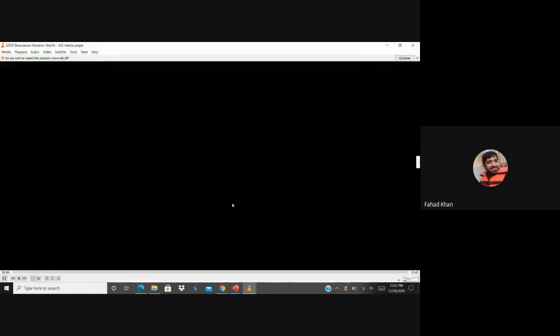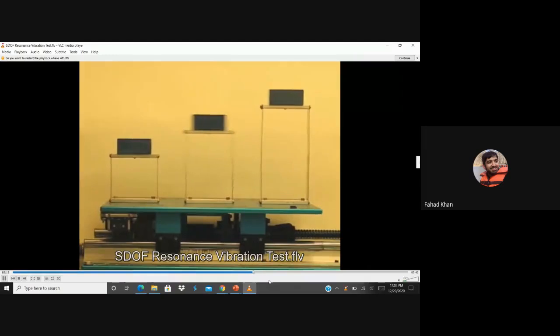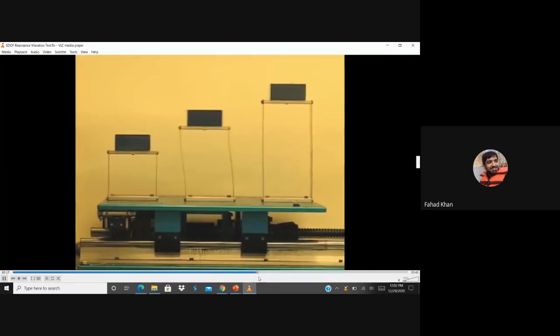And the taller structure should be at rest conditions. Okay, so here we have the medium structure vibrating, and now look at this structure, the taller structure. It has an R omega value of 2.84 almost, and it is not vibrating. It is vibrating at about 15% of static displacement, which is very small as compared to the short structure here.